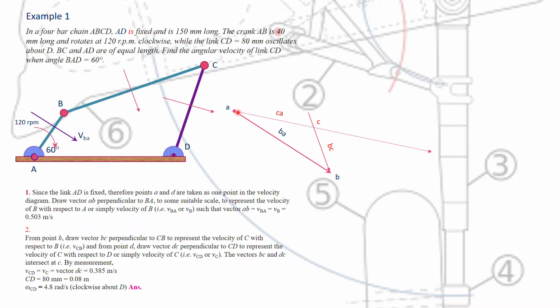Once you have got this line drawn from top to bottom, then from point A again, or D, because D here is DC. That is why I say put A comma D. So from point A or point D, you draw a line parallel to this component here. When both lines intersect, you will get your C here, the lowercase letter c, not the uppercase letter C. You must be able to differentiate what is the space diagram and what is the velocity diagram. So this is your point C.